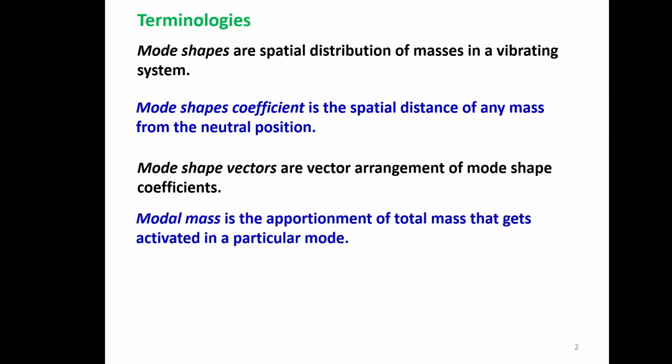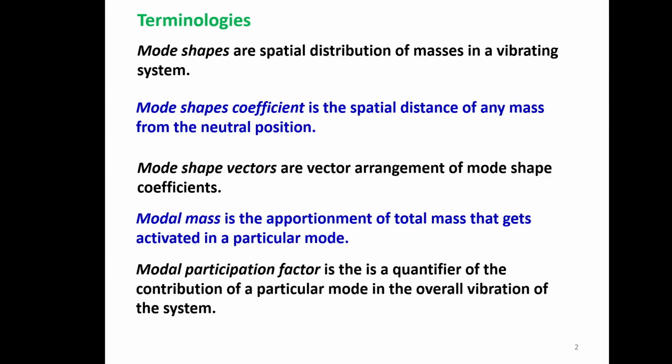Modal mass is the apportionment of total mass that gets activated in a particular mode. Modal participation factor is the quantifier of the contribution of a particular mode in the overall vibration of the system. So this we shall be encountering again and again in our studies.